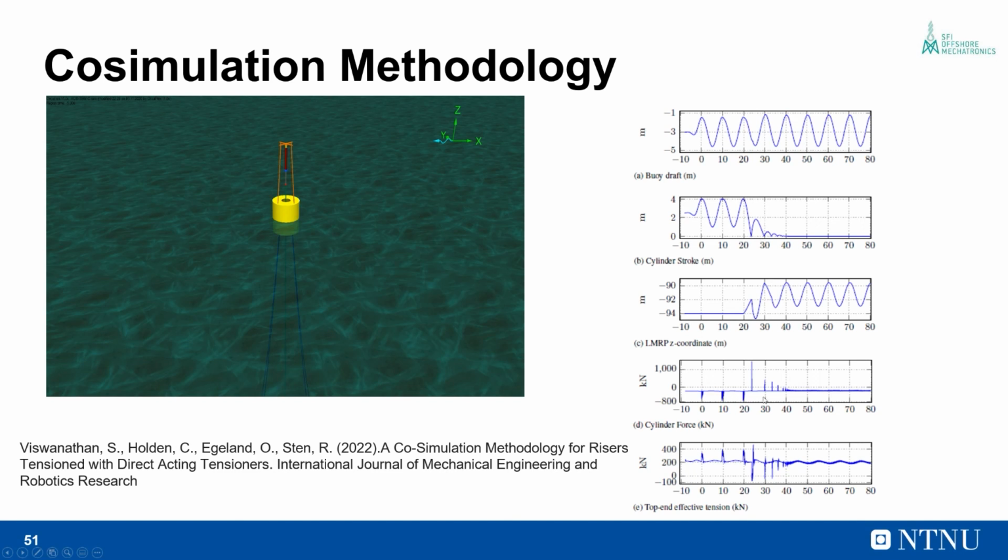We can also see what happens when the piston hits the top end. We see that again the top end goes into compression, and we see a corresponding response in the effective tension at the top end of the riser, where the negative stress means compression. And so this is the advantage of the co-simulation methodology, where we can get results from both the multiphysics software as well as the ocean engineering software.